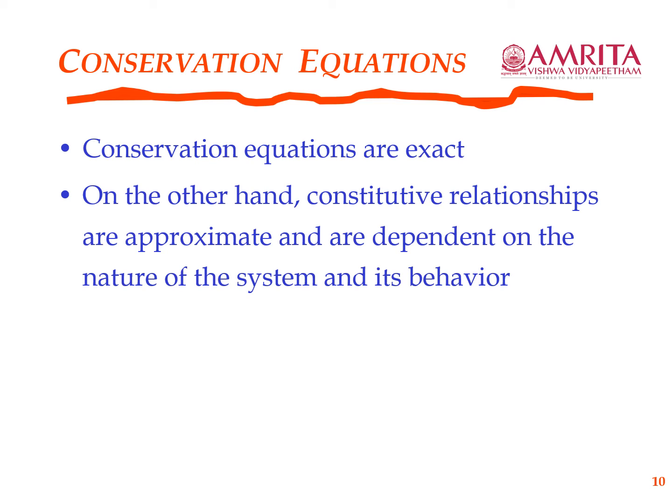Where do these terms go? In your conservation equation, when you write a species balance, for example, you have to write a flux for diffusion, which would be your Fick's law of diffusion, and then you will have to write an expression for a reaction, which could be a first order kinetics. So basically, while the species conservation is exact, for each term in that conservation you are saying that this is how much of that species goes into this particular way of leaving or entering the system.